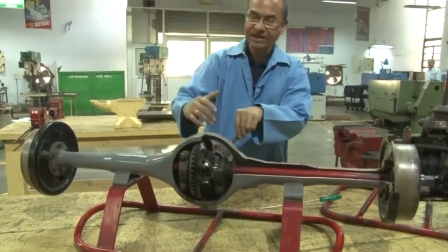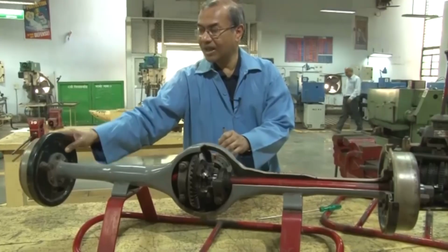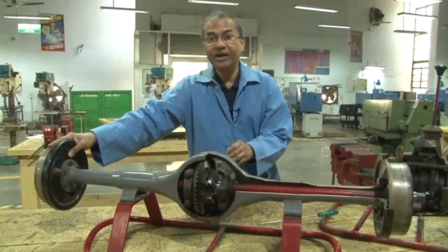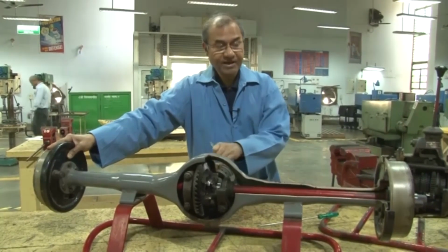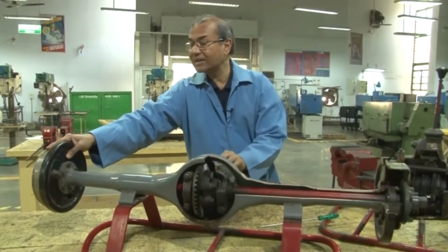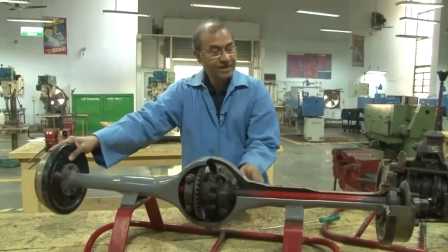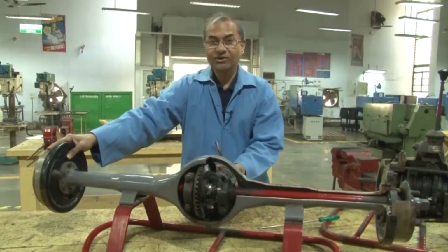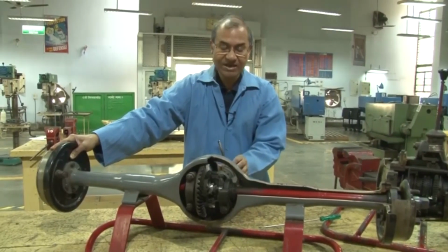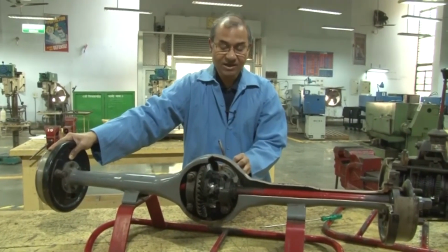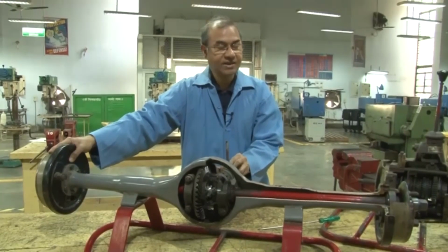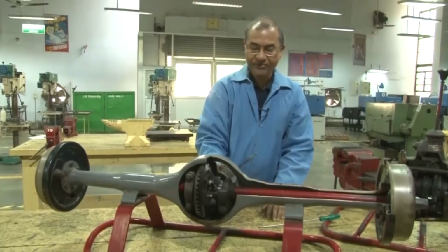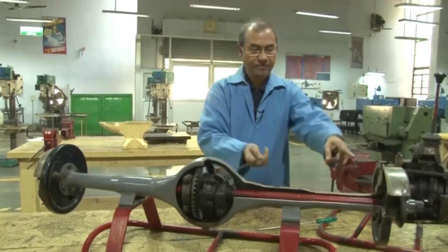But when it is taking a turn, suppose this wheel has less velocity, let us say 0, taking a very abrupt turn. In that case, this is stopped, as you can see that this is not rotating, but still this is rotating, because the input shaft is rotating at a constant speed. There is no change in the RPM or the speed of the input. So, this is the constant one.